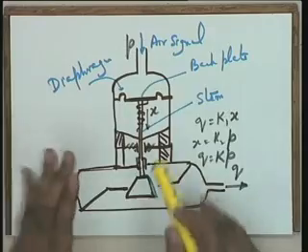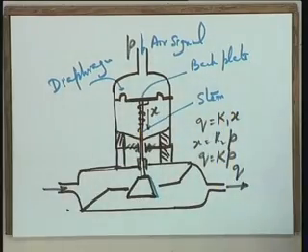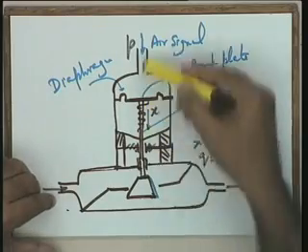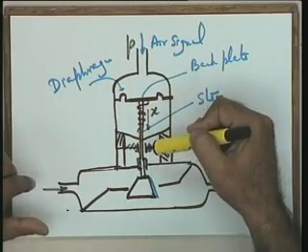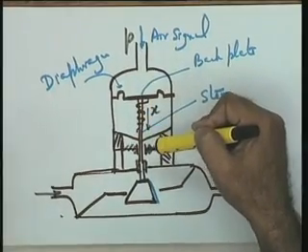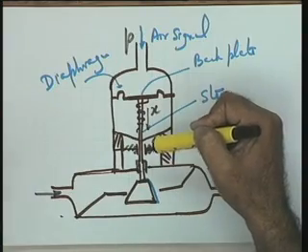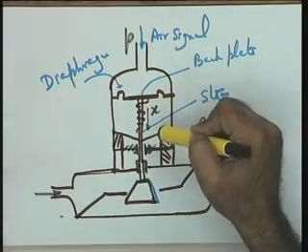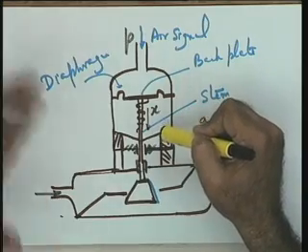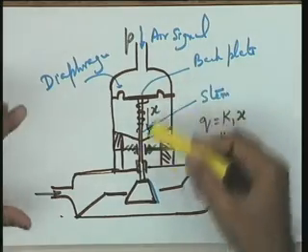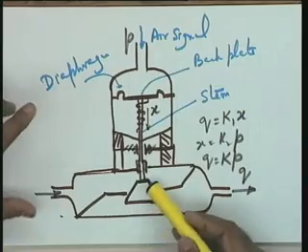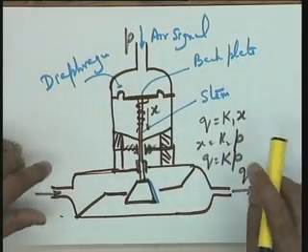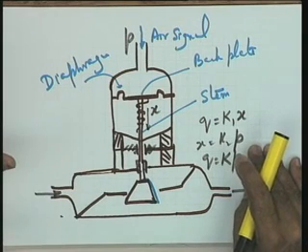When these control valves are very large, the power requirement to move this stem is high, and solenoids normally are not able to provide that power, while the air signal, that is this particular device, is able to provide the required power. In process control applications where large powers are required to move this stem, normally air operated control valves are used and not solenoid operated control valves.